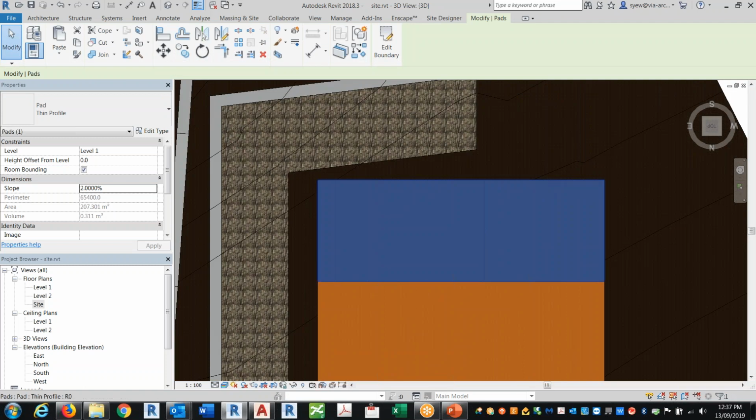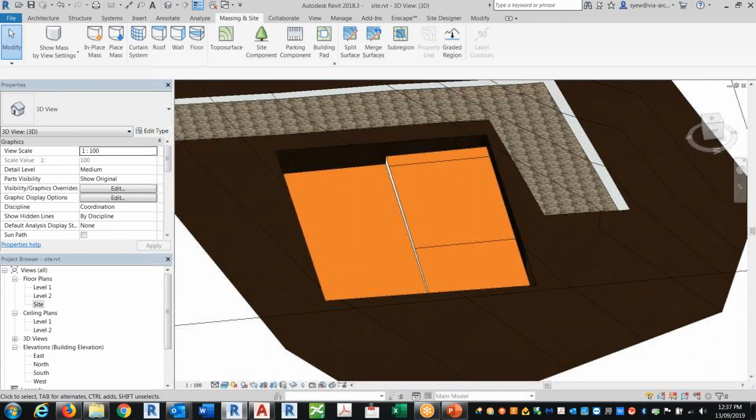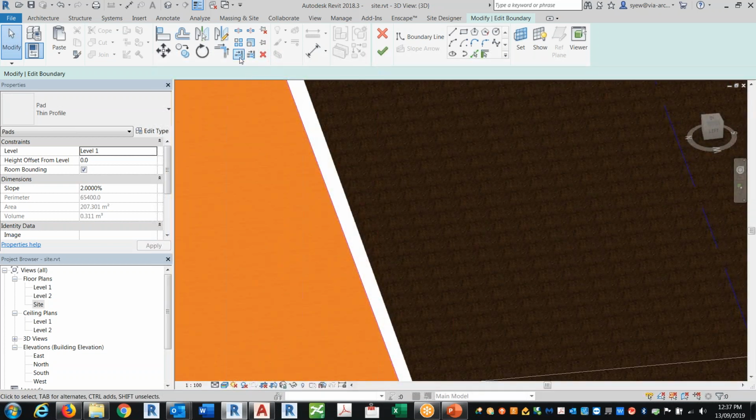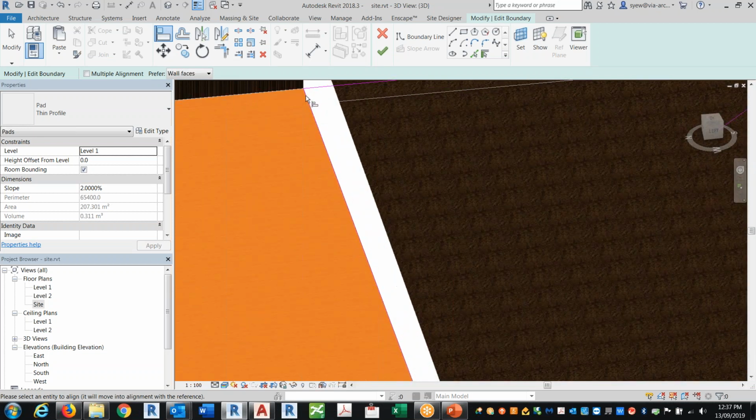So what is the alignment tool? Oh, the alignment tool. You can just type AL, or use this one right here. Then you pick that edge, and pick the edge of where you're going to draw it, and it will close up that gap. Does that potentially change angles to make them meet in the middle? It will, sure, yes, that's correct. Sometimes if you have an angle that's off a line, it will just match it to that particular location.